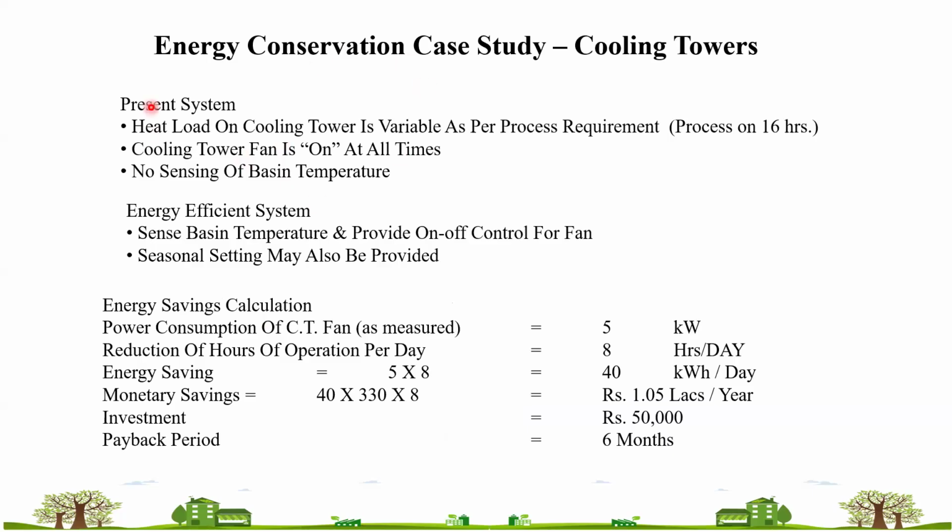Go to the last slide of this system. Here the heat load on the cooling tower is variable as per process requirement. The process is on for 16 hours, but the cooling tower fan is on at all times. There is no sensing of basin temperature in the present system.